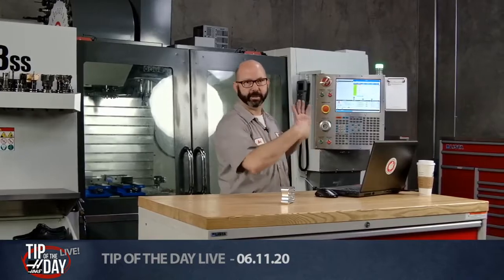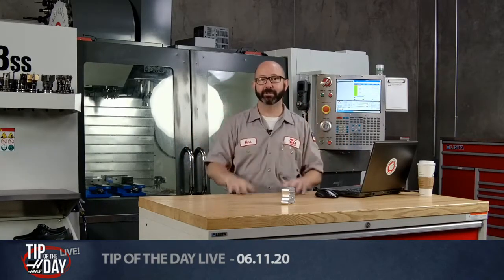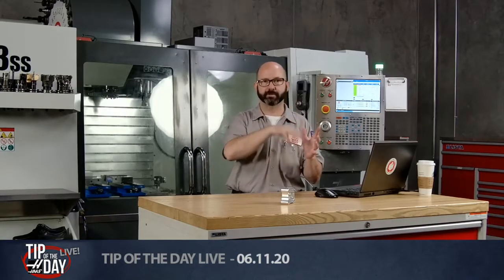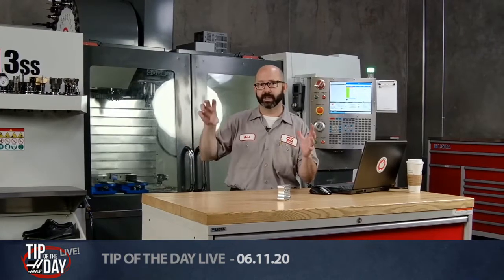When I first walked up to the HAAS lathe and I wanted to program on the sub spindle, the secondary spindle, right? Not the main spindle. I was confused because what I was used to in the past was having a different G code for the sub spindle than I did for the main spindle. So if I had 50 G codes for this side, I had 50 more that I had to memorize or look in the manual and relearn for the sub spindle. HAAS doesn't do it that way.